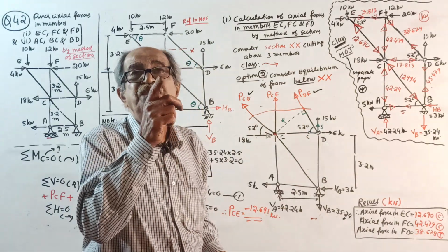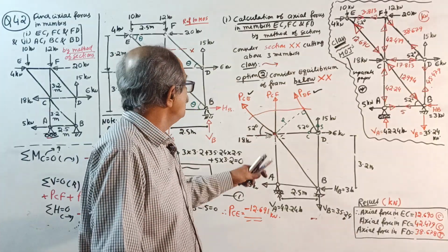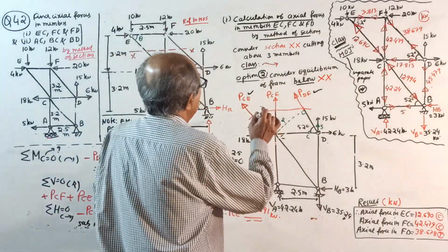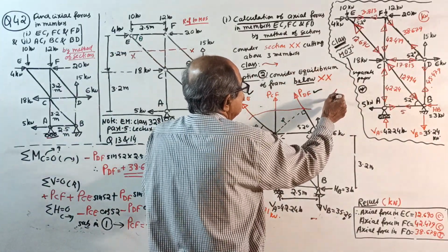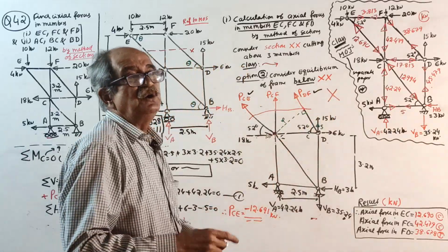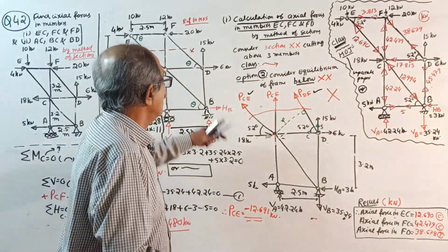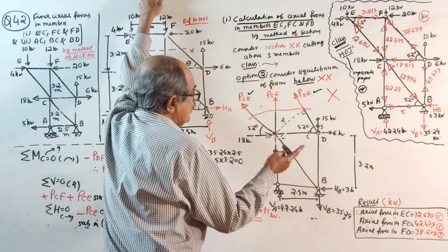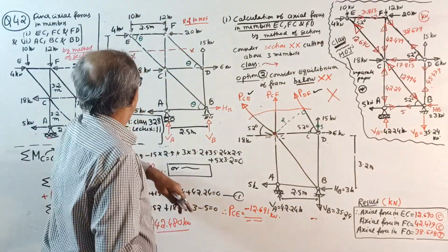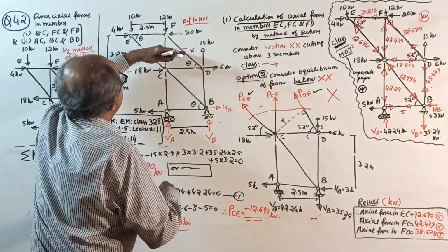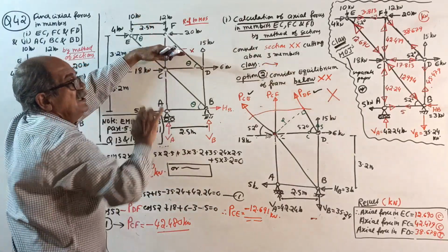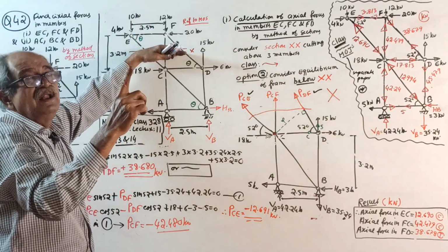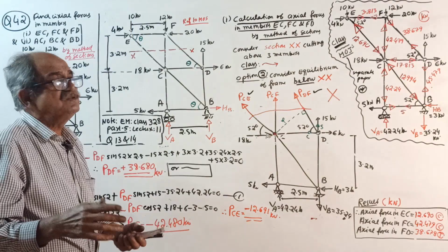See, that is 52 degree, 52.001 degree, now count it here. Actually, remember, looking below is not advantageous. Two drawbacks right here. First of all, huge calculation. Second drawback, reactions are required. So make a note here: cutting here and looking at the upper side is the easiest solution. Why? Small part, and second, reactions not required.